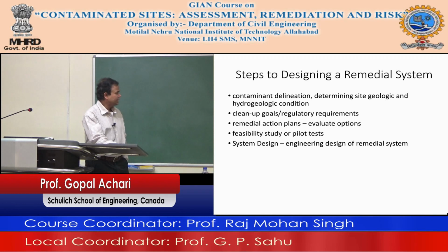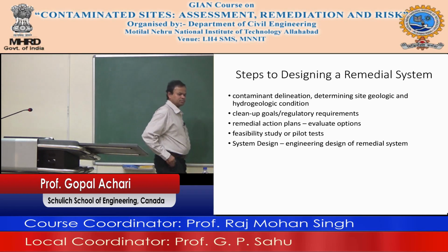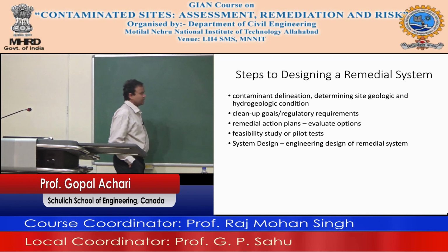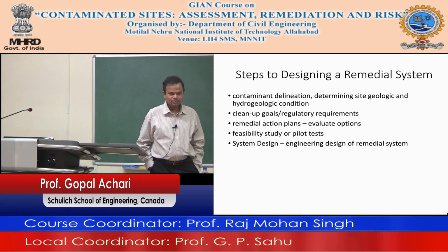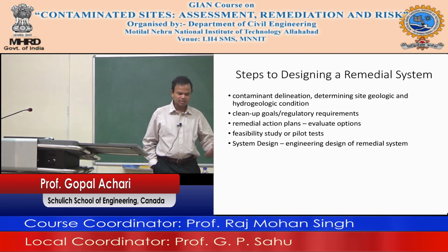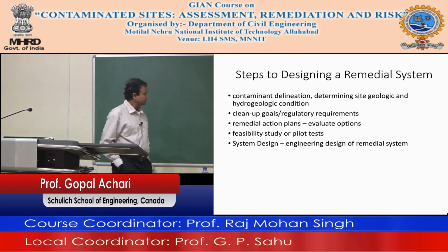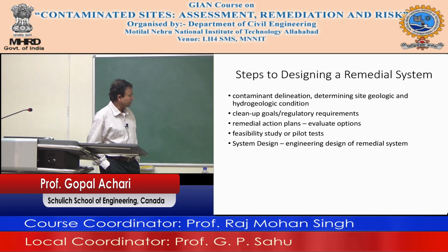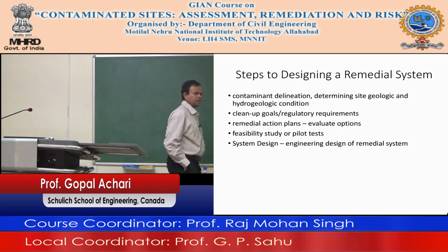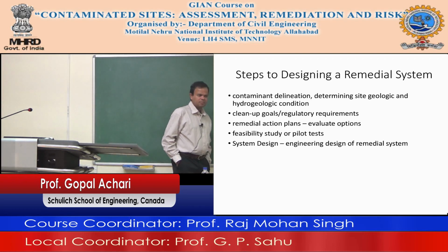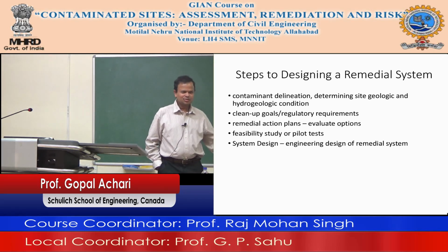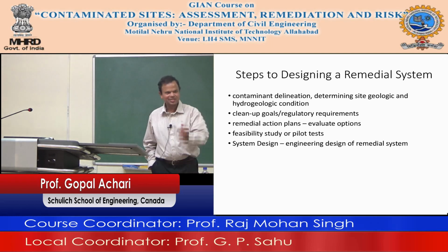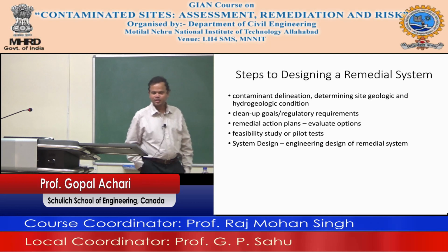You have to come up with remedial action plans, evaluate the different options. Quite often, multiple different remedial options are possible. You have to conduct a feasibility study or pilot study, okay? Because you need to know how that particular environment, geology, whatever, actually works with what you have tried to come up with. For example, if you're doing solidification, if you're using cement to solidify, you need to know what ratio of cement and contaminated soil you can use. You can read a bunch of papers, but that's not going to tell you what you have to use on that particular site, right?